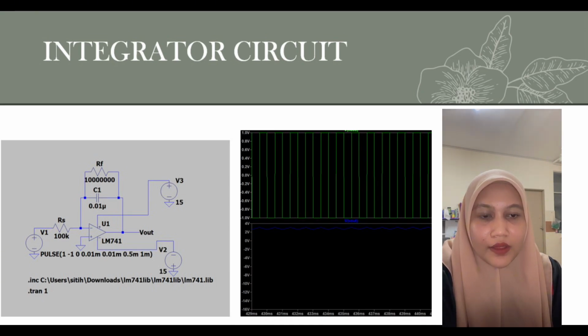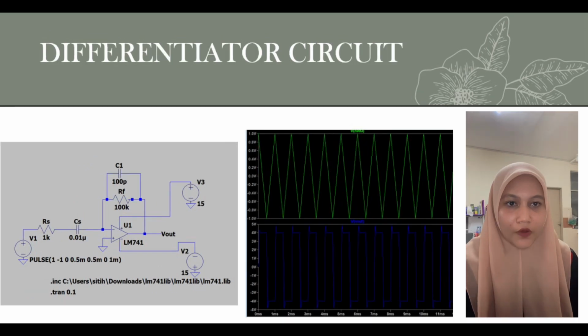The main analytical point here is the inclusion of the large 10 MΩ feedback resistor on the schematic. It is a compensation technique. Its purpose is to manage tiny input bias current and prevent DC drift, which would otherwise push the output into saturation very quickly.